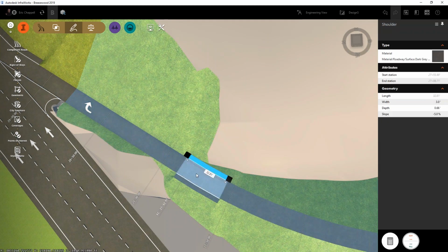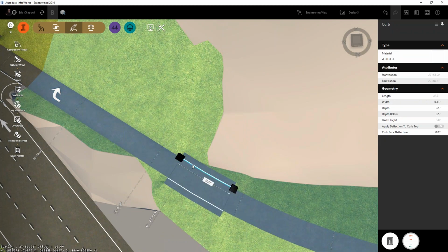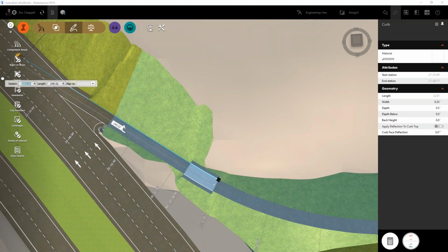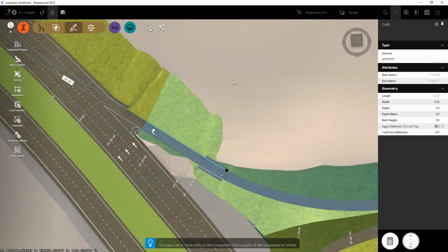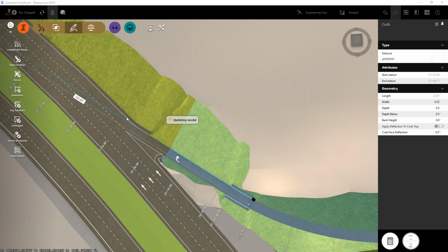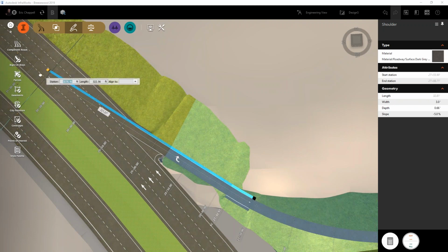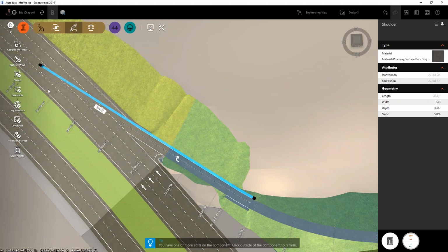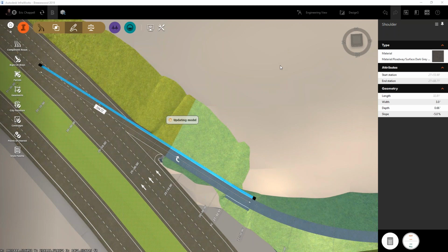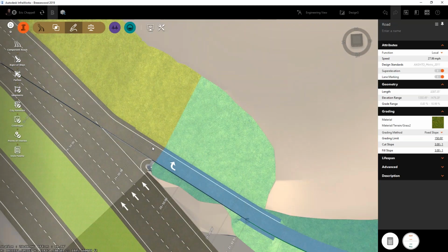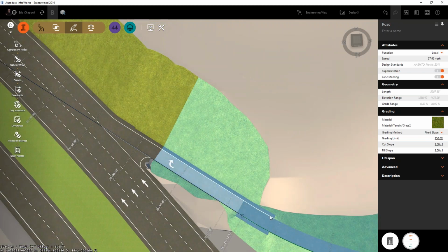But now that I have this, I can click these individual components and stretch them to where they need to be. Now this is where things can get a little interesting. Sometimes you need to stretch the component the whole way into the intersection, which is what I did with the stripe. And you'll get a nice merging of the two components. Okay, so that worked well. The shoulder, let's see how that works. I'm going to do that with the shoulder. Again, I'll click off the road and I can see that. Now the shoulders look good, except they are different widths, so you'll see a little bump right there.